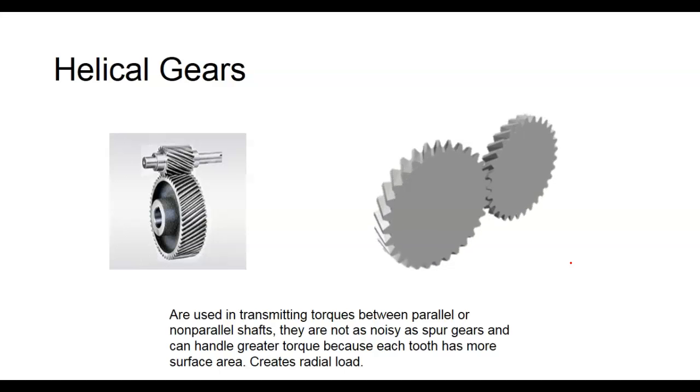And it has absolutely no effect on the multipliers because it just cancels each other out. In the video, he actually did the math. So about the only thing we use idler wheels or idler gears for is to increase the distance between the driver and the driven. And it also allows the driver and the driven to spin in the same direction. That makes sense? And the size of the idler has nothing to do with whether it's a torque multiplier or a speed multiplier.